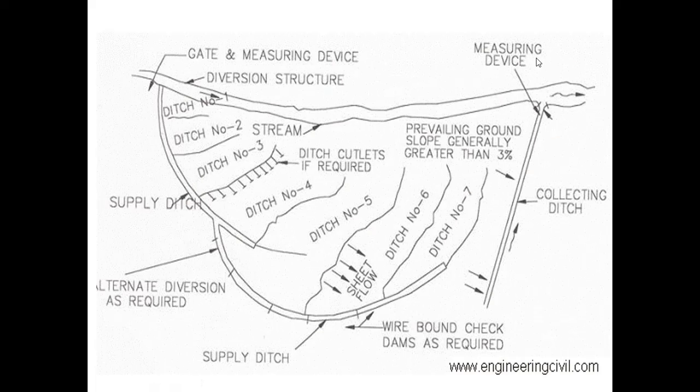This is the ditch and furrow method. In areas with irregular topography, shallow, flat bottomed and closely spaced ditches or furrows provide maximum water contact area to recharge the water from different types of sources, stream or canal. This technique requires less soil preparation than the recharge basins, the previous method, and it is less sensitive to silting. Generally, three patterns of ditch and furrow system are adopted: lateral ditch system, dendritic pattern and contour pattern.